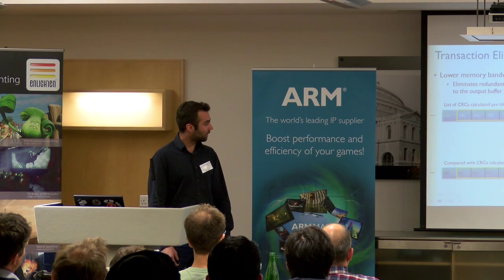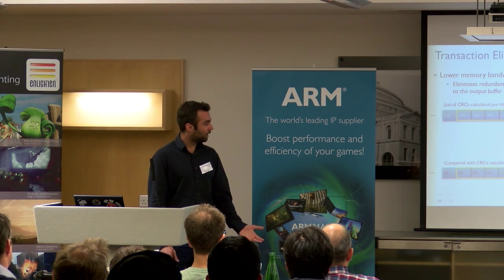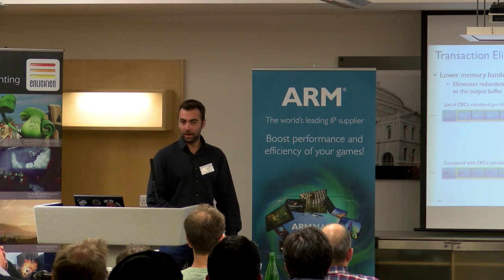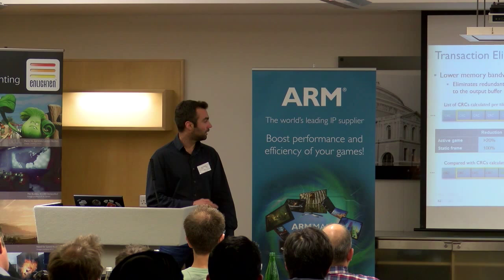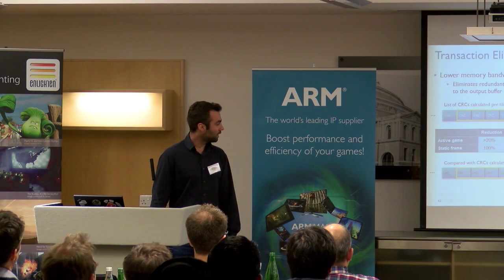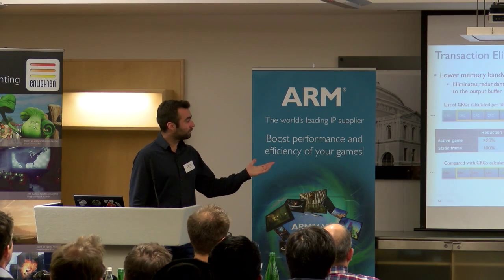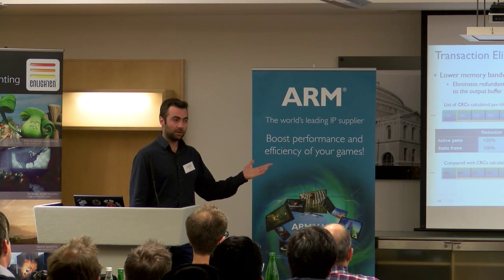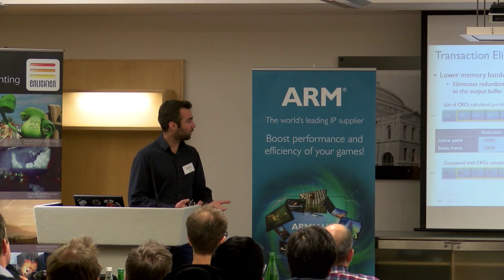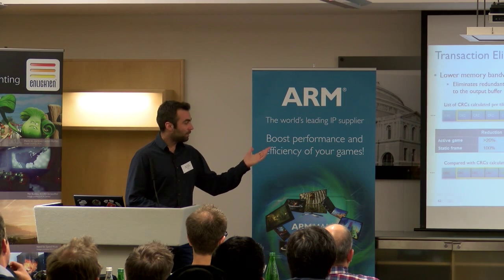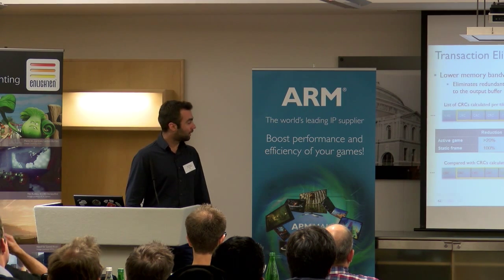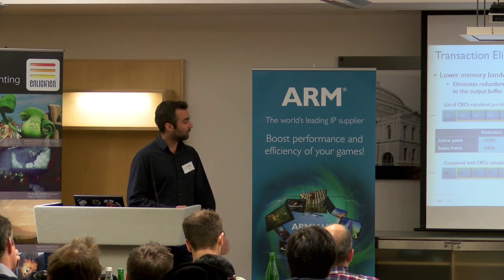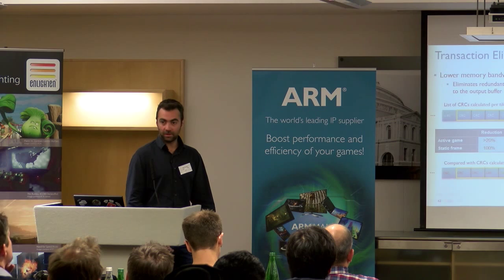And in this case, we are saving lots of write bandwidth because we don't have to rewrite the redundant part of the scene. So for static frames, you can have a 100% reduction of write-out bandwidth. But even in highly dynamic games, we have seen that maybe 20% or more of the tiles still remain static, and you can have good bandwidth savings from that.